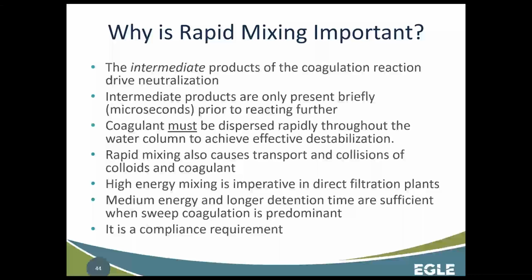So we were just talking about contact sport. High energy mixing is imperative in direct filtration plants. You're not going to get the benefit of having flocculation steps. Medium energy and longer detention times are sufficient when sweep coagulation is predominant. And finally, at the end of the day, it's a compliance requirement. You need to do it. It's in the rules.